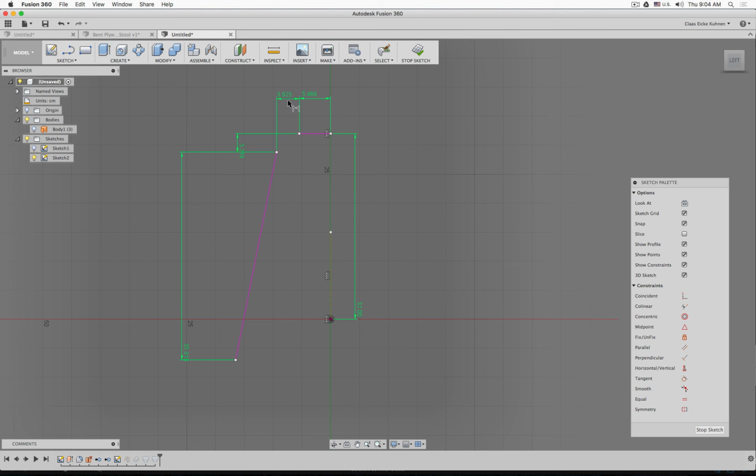and maybe this and this, and I think no, I can move this one up and down. Okay, and up there, this one you saw got a little bit funky, so I want to make this line horizontal. So now there's nothing I can move anymore. Basically the sketch is secured. And the way how I put the dimensions down is just one easy way. I was just thinking, what are the easiest logical blocks? So I want to specify a distance between these 2 points by along X and along Z.